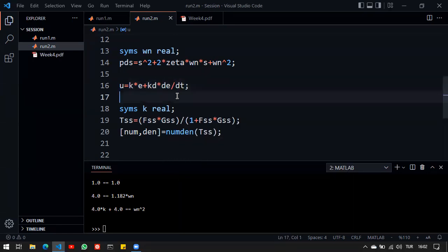Now, this is a different controller. This is the PD type controller. I have a proportional part. I also have a derivative part. Now, depending on the system, since we're dealing with dynamic systems, it will look at the changes of the error. So if it's, for example, an aggressive change in error, then I will apply a higher control signal to the system. So it will behave differently.